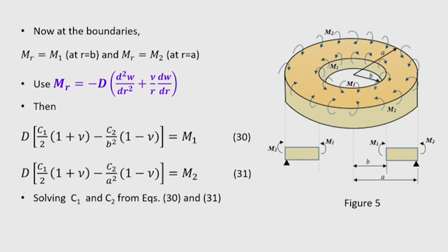Okay. So, at the inner edge the moment that is applied is b, and it is a symmetrically applied moment, edge moment uniform along the inner periphery and outer periphery. So, it is bending under the symmetrical moment, because if the moments are antisymmetrical then the axisymmetrical condition, the differential equation cannot be used. So, m 1 is existing at the inner edge.